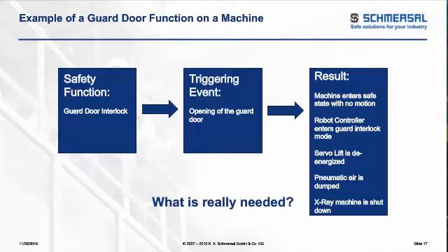We got to really focus in on the robot, but not think about the other output devices that can also be just as hazardous as the robot. It may not be as high of a hazard, where maybe the robot can amputate you, but one of the other things can certainly crush your fingers, for example, on the pneumatics as an example. Are we safely shutting those down per the safety level required based on our audit?